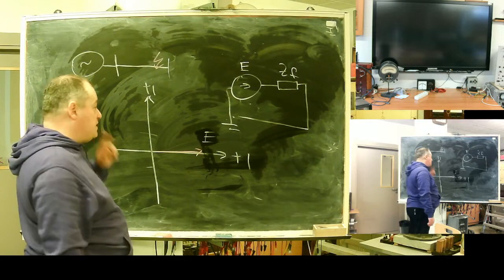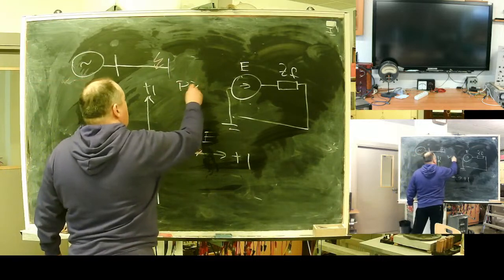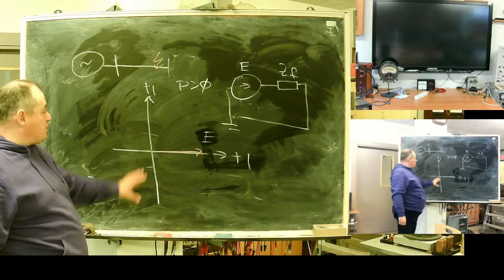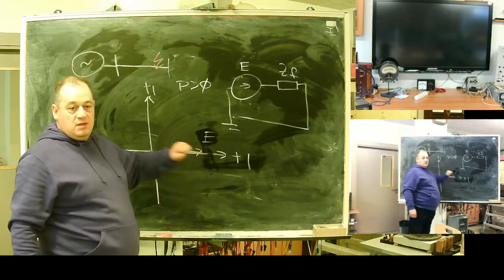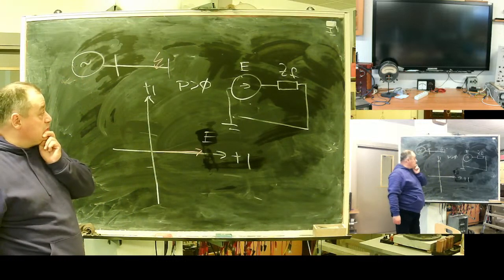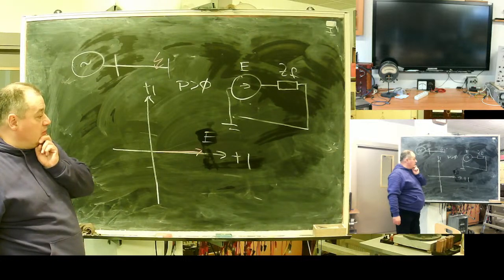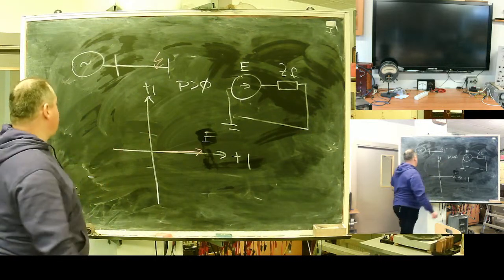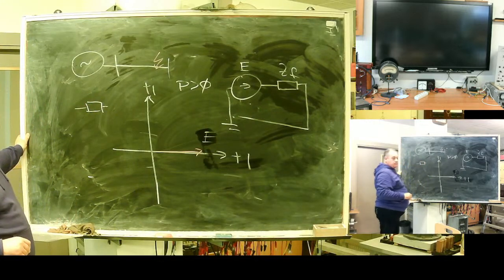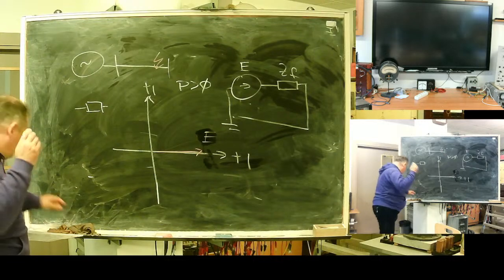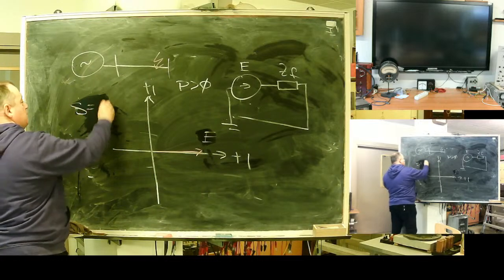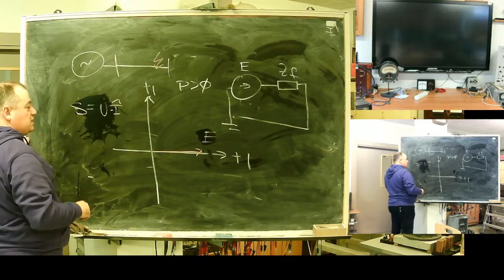How the characteristic of relay power greater than 0 will look on this plane. It's a complex plane. I've assumed a real voltage. For example, ZF is pure active. More simple: power is voltage times conjugated current.